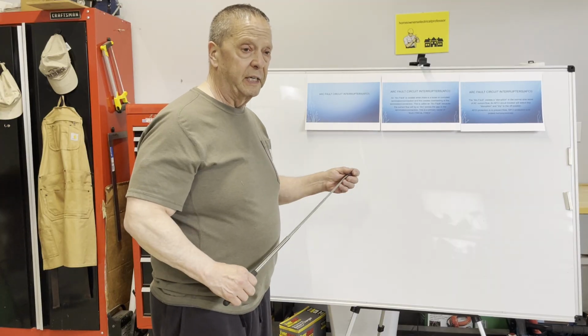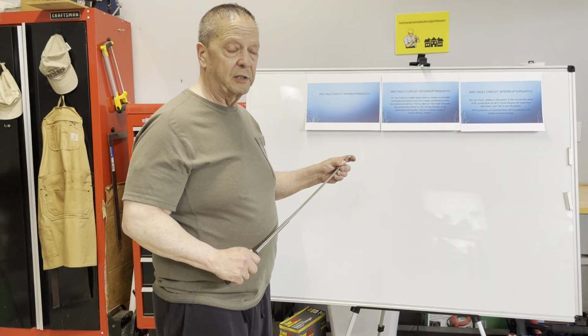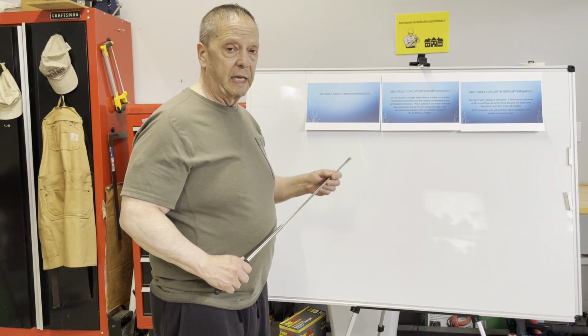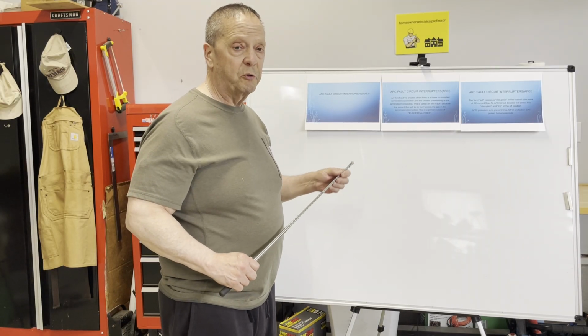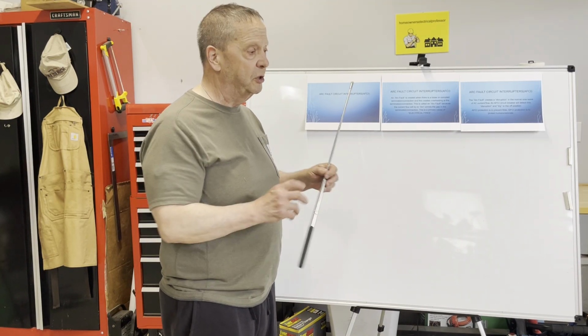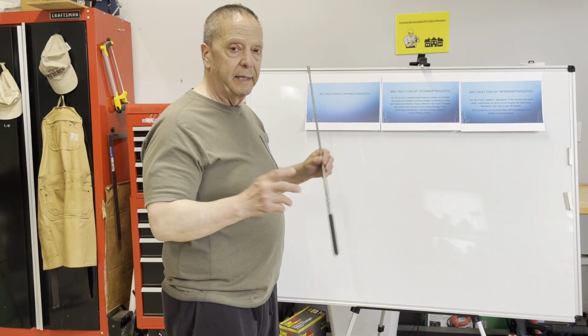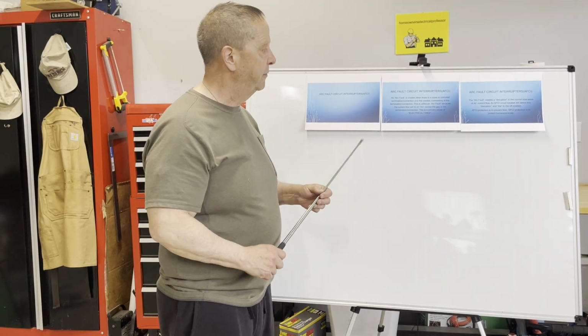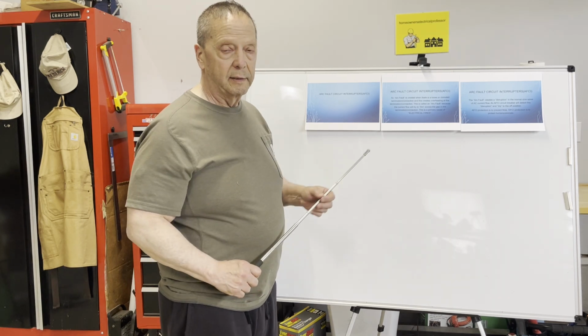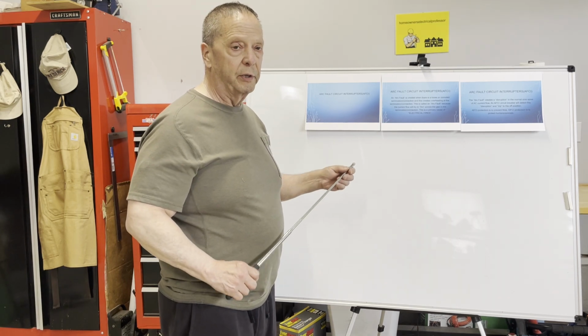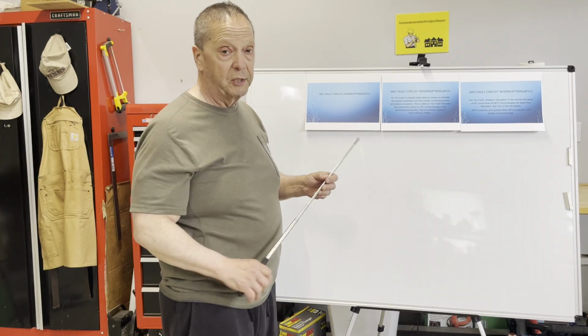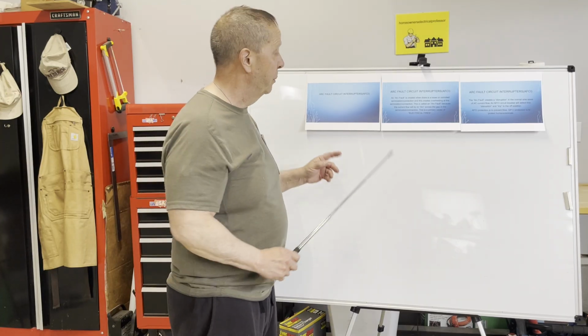Earlier on in my videos, when I was talking about basic electrical theory, I made a statement that the weakest link in any electrical system is at the connections or the terminations. Wires normally just do not go bad in the middle. It's wherever you have a connection. So all your connections are important. Look at my videos on termination and connections for more information.